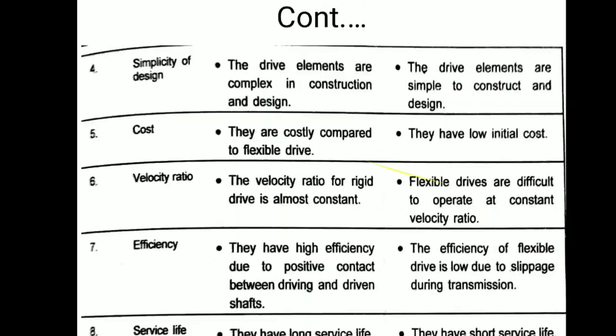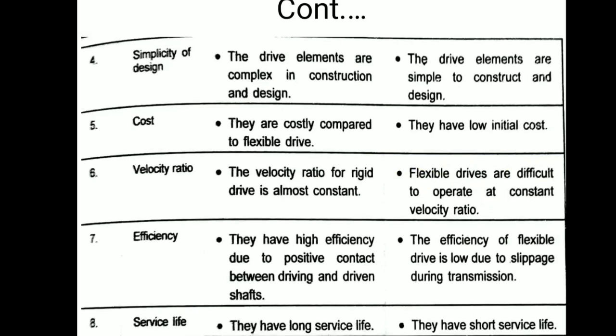Okay. Fourth point, simplicity of design. In case of rigid drive, you can see the complex design is there. Why? Because we need to design a tooth, the terminology, their force, various effective loads, and through that we decide the design. But in case of the belt, we can just design the pulley on the basis of load, and accordingly select the belt drive to transmit the motion and power very easily.